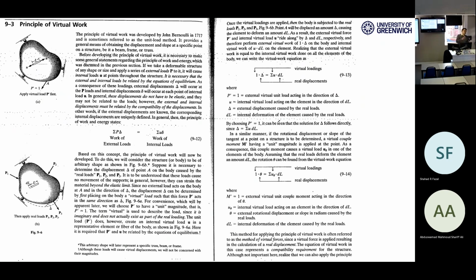As you see, we are progressing through the different methods. The integration method was able to only consider bending moment. They were dealing with the problem only by considering bending moment, and they couldn't account for shear deformation or axial deformation. We stepped forward to Castigliano, which is a kind of energy-based method.